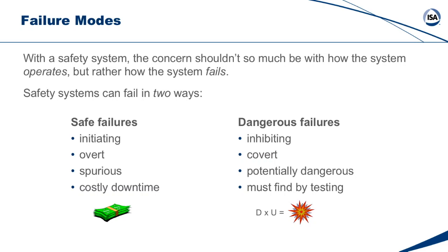Actually, they're potentially dangerous. Just because the isolation valve that's been open for the last 2 years is now stuck, that does not immediately cause a hazardous event. If there is a demand at the same time that the device is unavailable to do its job, that's when you might have your hazardous event, as that little equation and graphic shows.